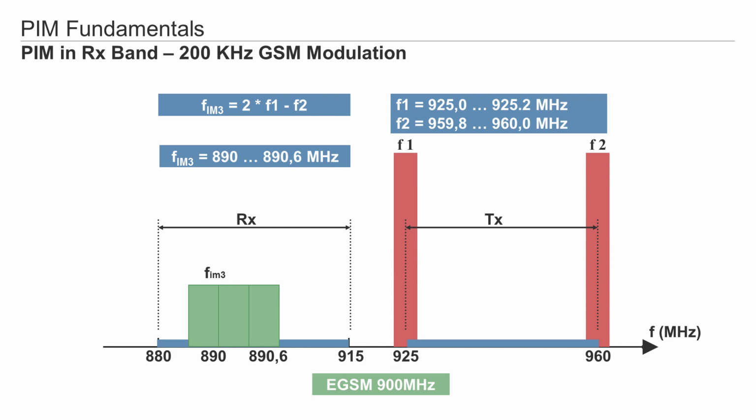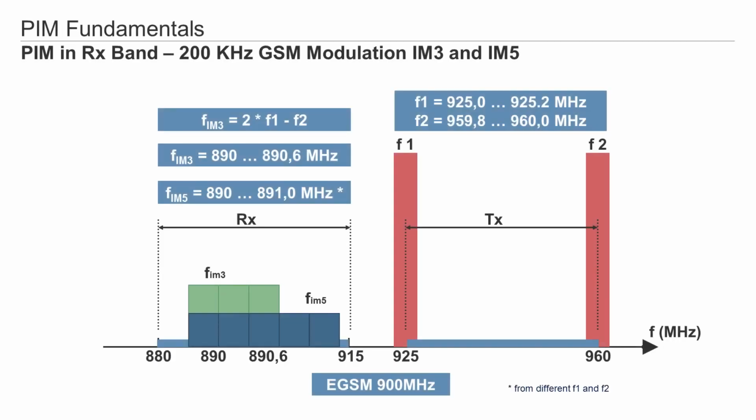Things get more critical if each carrier has several frequencies and services on one site location. Also, because of site sharing, different mobile network operators can be located on one site. If the PIM level is very bad, the 5th order of PIM will occur, blocking the RX channel of the BTS2. All this will cause more dropped calls, low data speed, and reduced coverage. If PIM problems are significant, the base stations can even shut down completely.